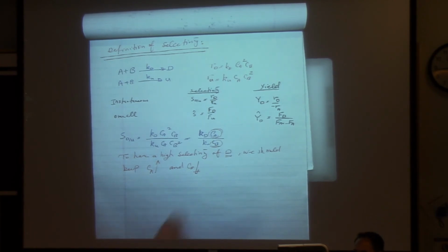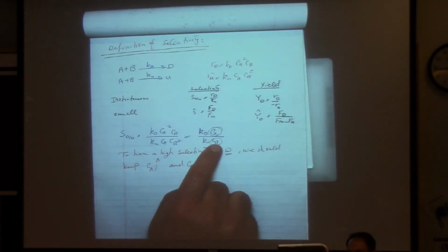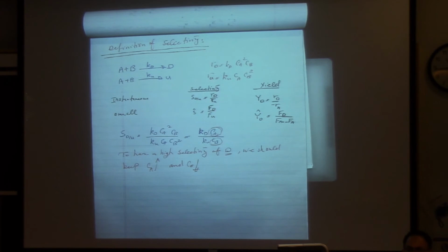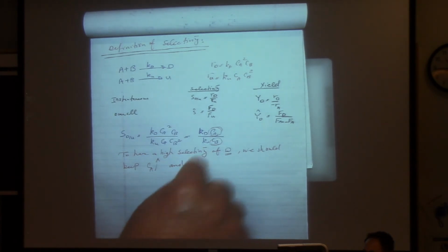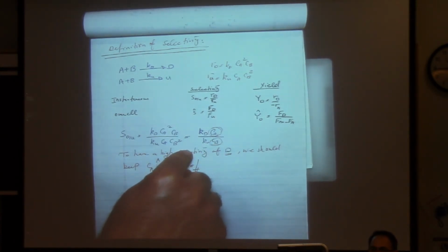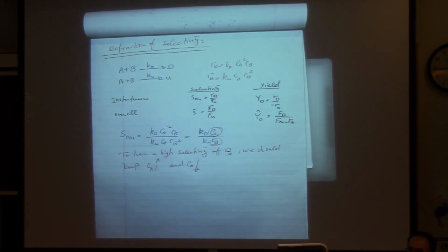Therefore, you keep the concentration of C_B low at any given time, and since you start with a large amount of A, your C_A is always high. That plays very well for this reaction. This is one of the applications of the semi-batch reactor.